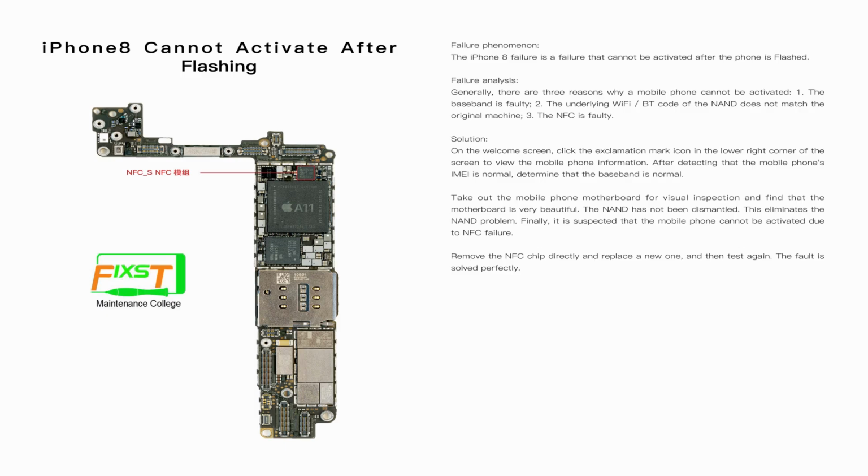On the welcome screen, click the exclamation mark icon in the lower right corner to reveal the mobile phone information. After detecting this phone, the IMEI is normal, so the baseband is normal. So we take out the motherboard to check it.